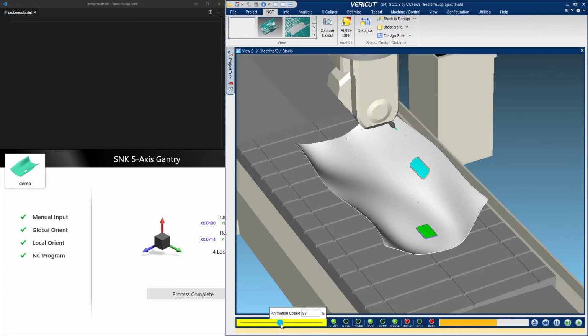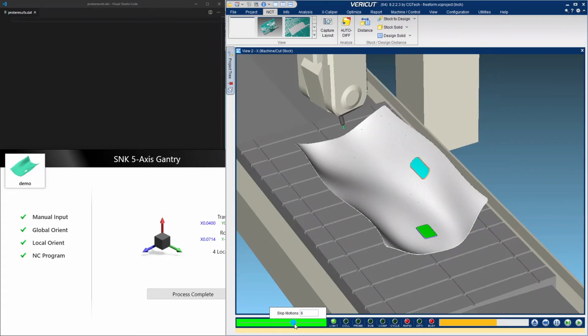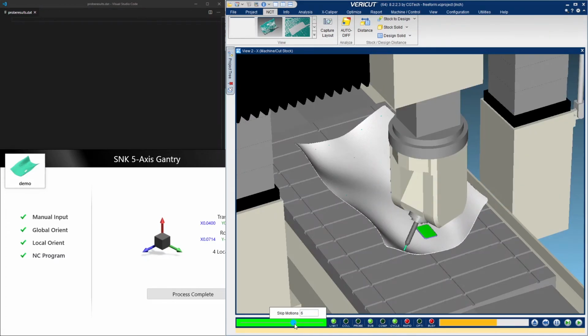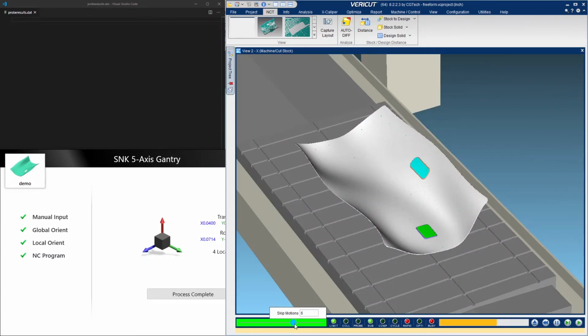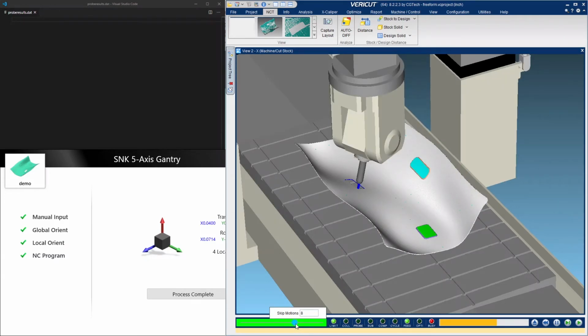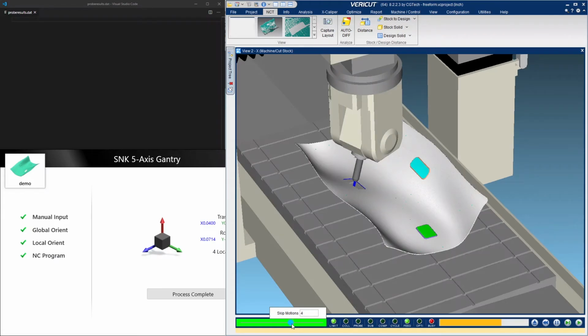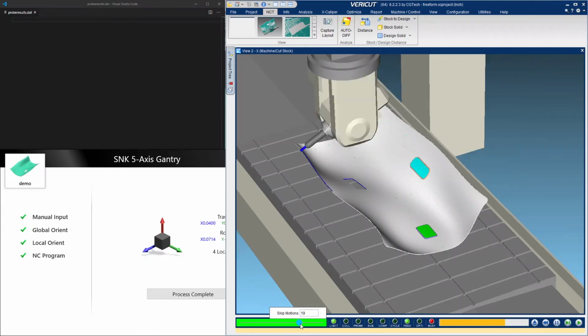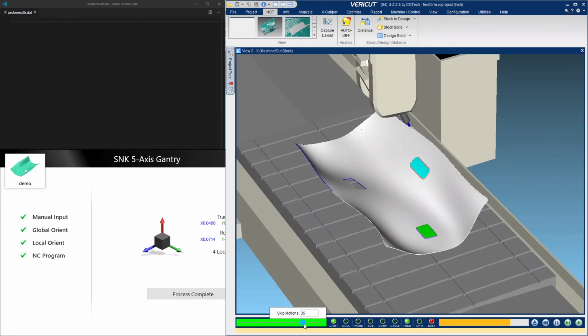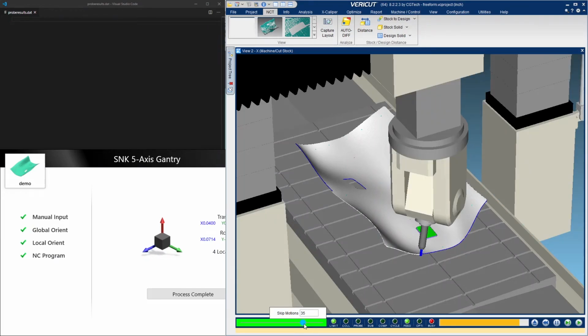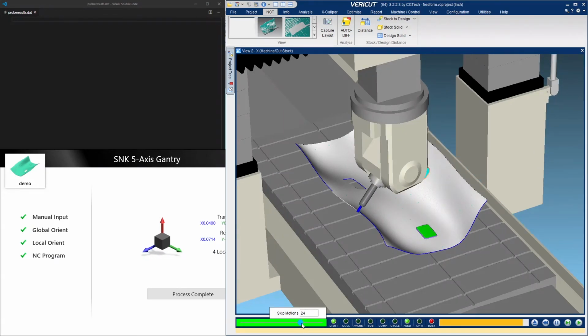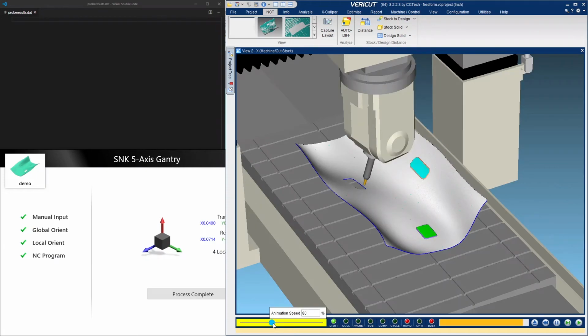Follow that up with the countersink, a 100-degree countersink. Mill out the cutout, and then finish that cutout with the same tool. Finish the periphery of the part. Again, a full 5-axis operation. And then lastly will be the chamfer tool to cut the chamfer around the pocket.